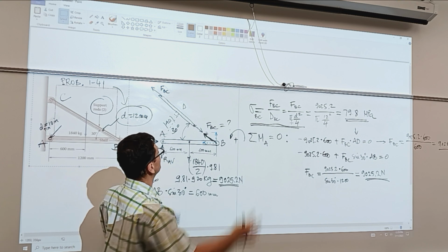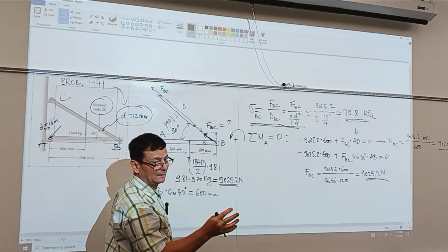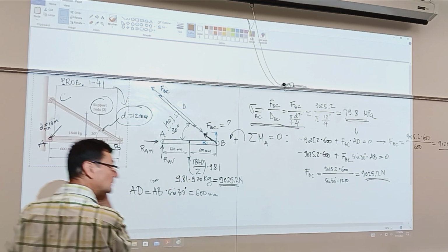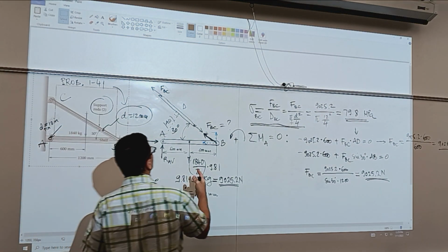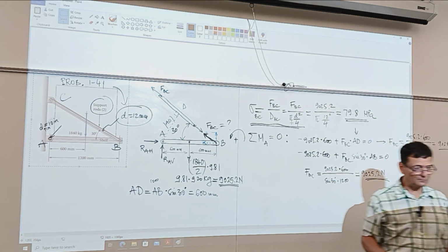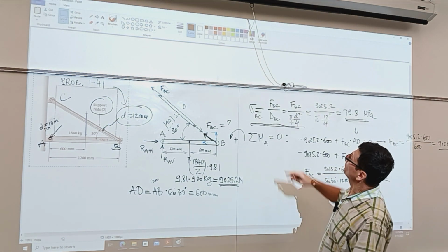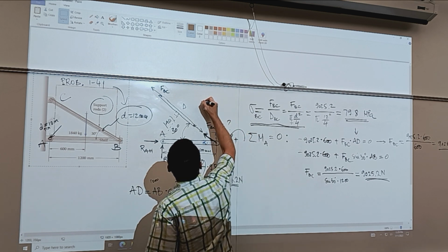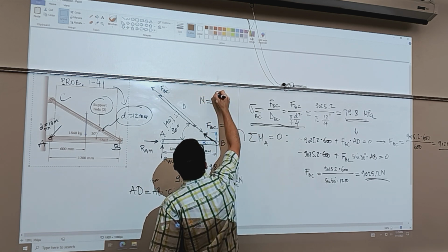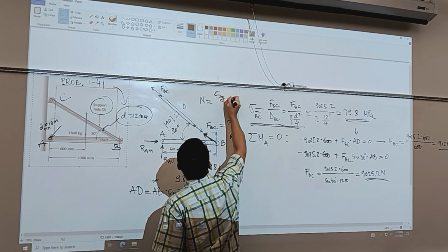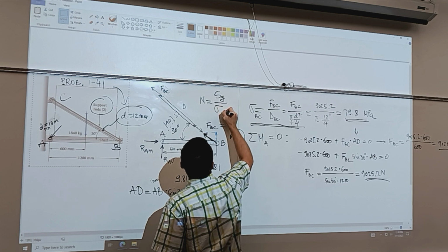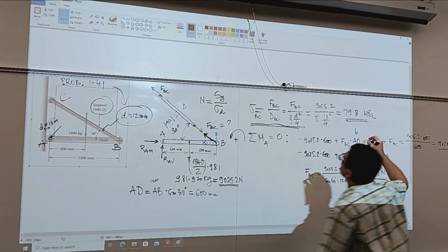But if the load is applied repeatedly, then you need to start thinking more about what the possibilities of failure are and what the design recommends. We haven't discussed design factor or factor of safety. That will be covered; I'm anticipating. So design factor N would be the ratio, let's relate it to yield strength over design stress sigma D. So let's call this design stress.